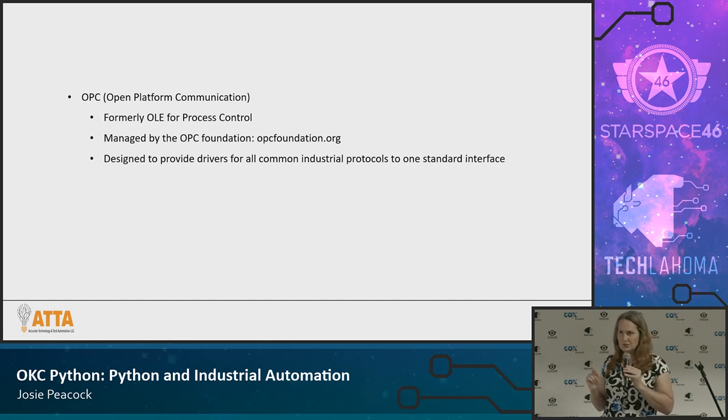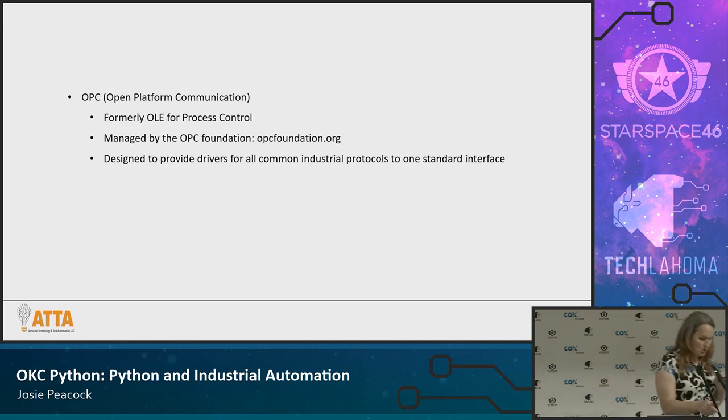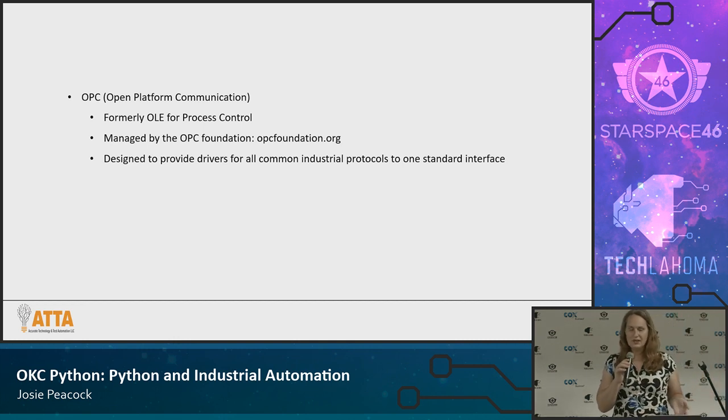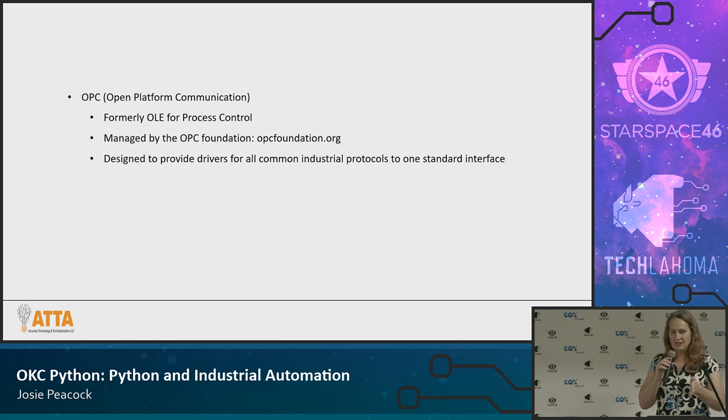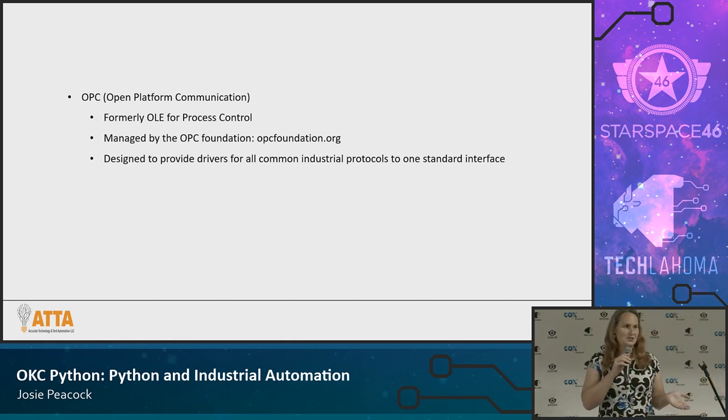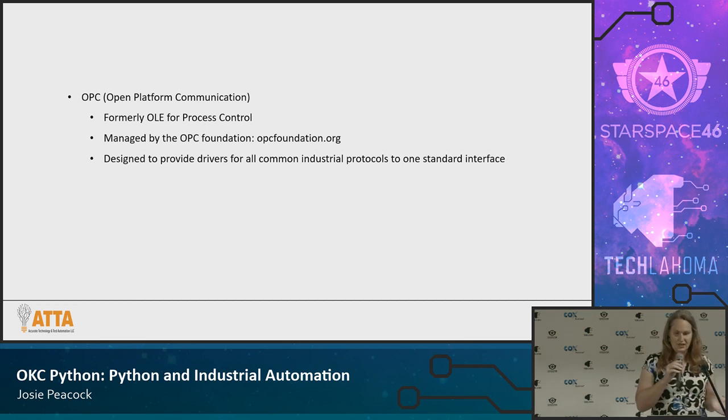Now they have what's called OPC UA, which is Unified Architecture, which actually I found a really nice Node.js program that reads and writes, and I found a few libraries in Python that I've not really had a chance to play with. But the idea of OPC is to take each and every one of these different protocols and put a driver in front of it, and you can connect to this OPC the same way every time. And it's designed for the industrial Internet of Things.